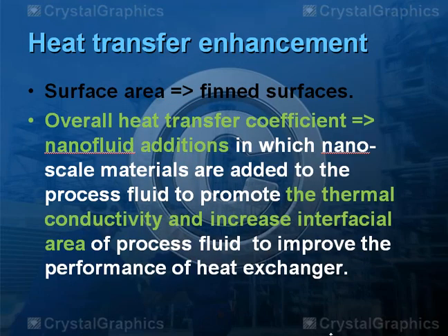To enhance the heat transfer in heat exchangers, we need to modify the surface area or to modify the overall heat transfer coefficient. The addition of nanofluid or nanoparticles additives is used to enhance the thermal conductivity and interfacial area of the base fluid.